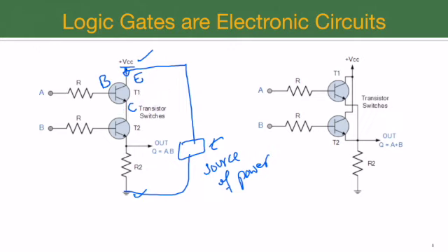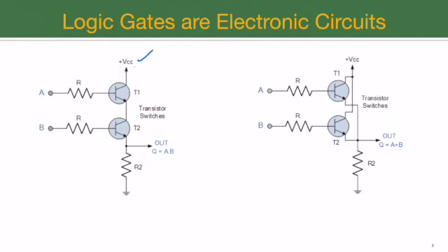So now let's look at how this particular circuit is an AND gate. You don't need to learn all of this, but knowing how computers work and what the basic units of a computer are helps you understand the working of the computer much better. The basic idea is that I will not say the voltage is applied, I will say that this value is always 1. Here I want to perform an AND operation between the bits 1 and 1. So I want to generate this result, which means I will apply a 1 over here and a 1 over here.